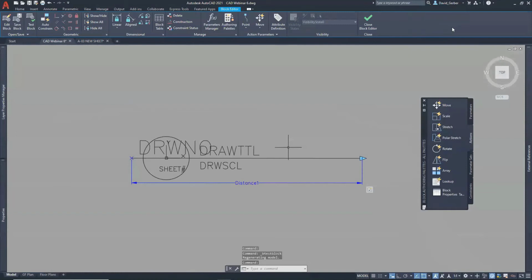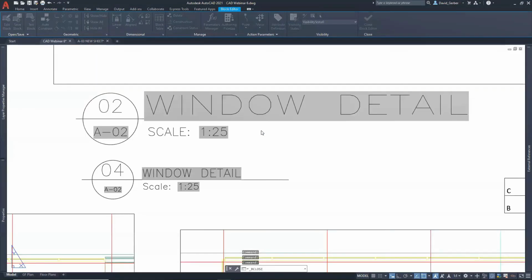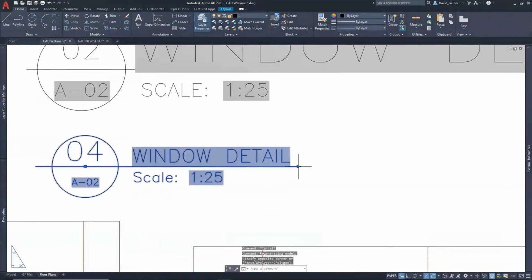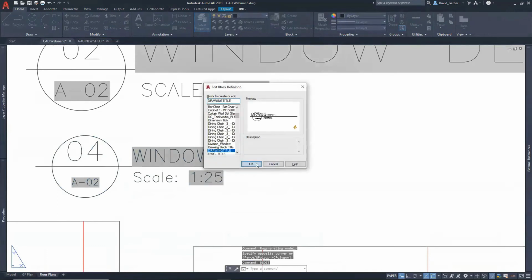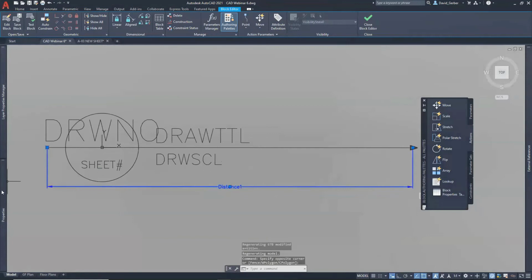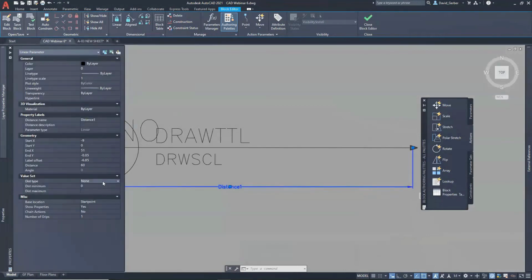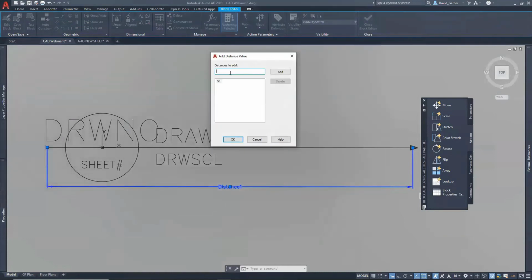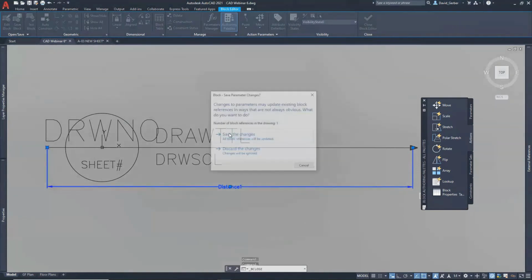So now in our drawing, it's basically just given us a bit extra stuff to work with. Again, if you want to make that a bit better and a bit more uniform in the office, we can actually start to adjust that distance. So just as we did with our grips, we can change our distance type to a list. So that way it's only a certain distance. So let me just bring this over. And you can start to add distances. So maybe we want to do 40, 50, and 70. Okay. And we'll just close this and I'll show you how it looks now.